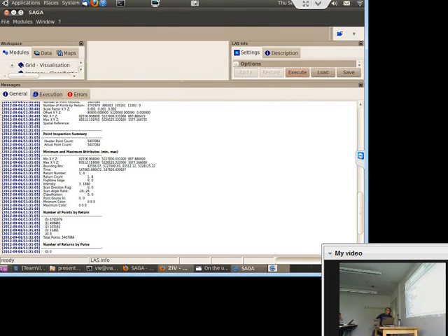intensity, a flight line edge, that is those points who are at the edge of a flight line when the scanner has its maximum angle. A classification could be stored if available for each point. So is it ground, is it tree, is it building, or stuff like that. And we could attach RGB color values to each point. And then we get a number of points per return listing. So we see we have about 4.7 million first returns, about 500,000 second returns, and so on. So the total point count is about 5.5 million points.